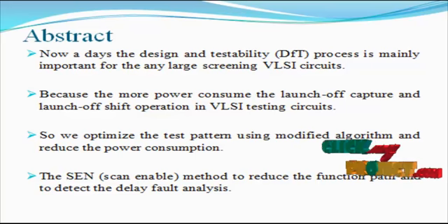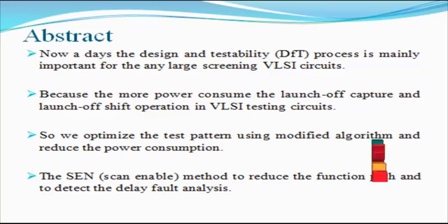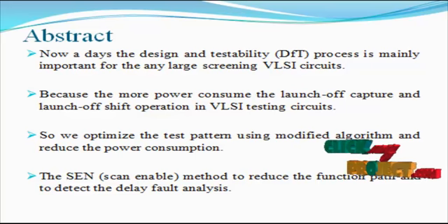The proposed DFT support enables a partition approach where any set of patterns generated in a power unaware manner can be utilized on one design region at a time, reducing both the launch and capture power in a design flow compatible manner. This way the test pattern count and the quality of the optimized patterns are preserved while lowering the launch and capture power.